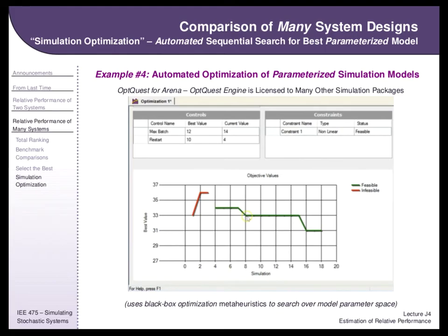And here are constraints, like I need to make sure this response variable never gets higher than this amount or lower than this amount. This could be temperature in a reactor. I want you to optimize the reactor performance, but even though energy production is the response variable to maximize, I do not want to maximize it if it means I'm at critical temperatures in the reactor. So I want to optimize my energy production subject to my temperature staying in safe ranges.